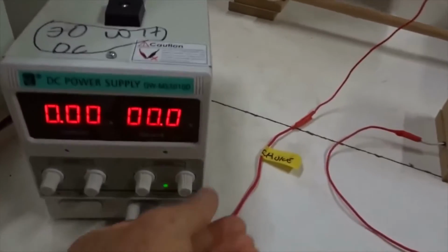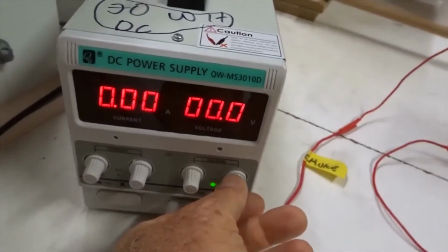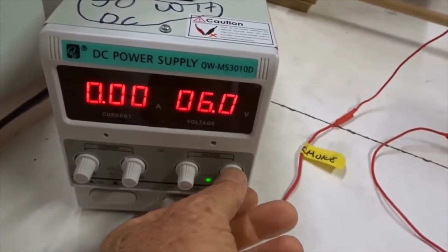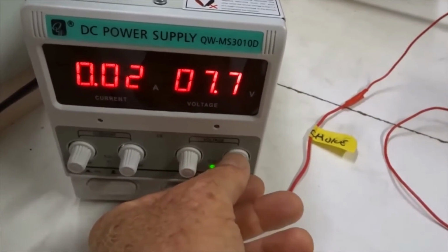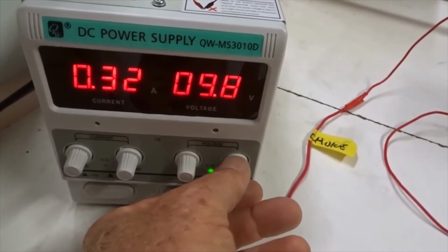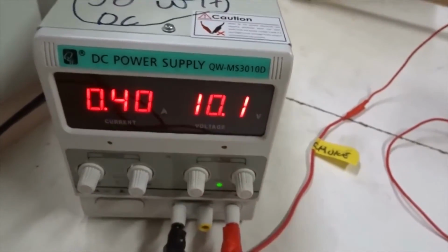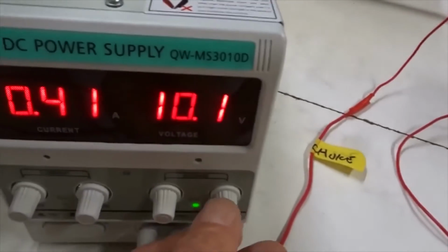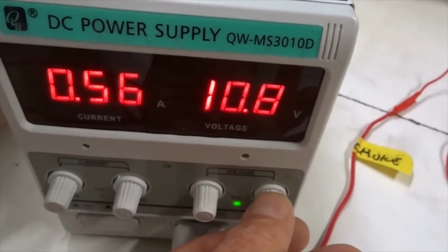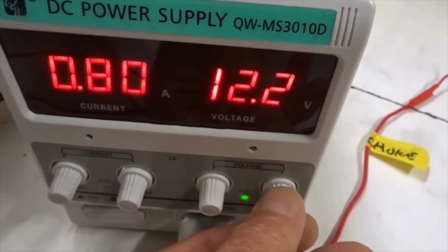Now there are two MOSFETs in series, so we need 10 volts to turn on the current. See, at 5 volts nothing's happening. Each has a 5 volt activation energy. We get to about 10 volts, the current starts to turn on, but we haven't got any oscillation in the secondary coil yet. Nothing's oscillating, still DC.